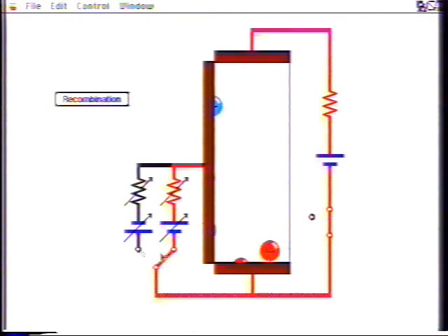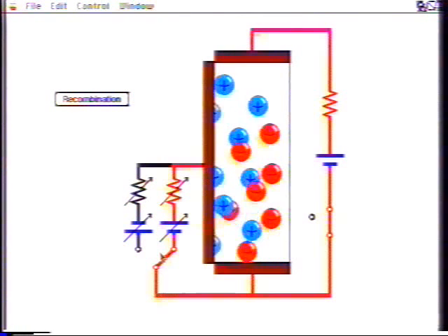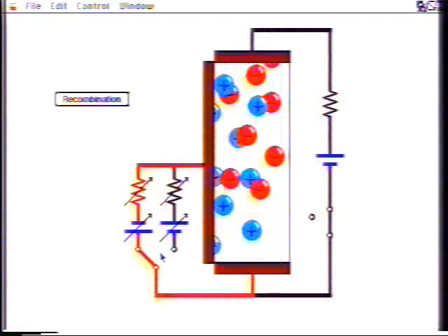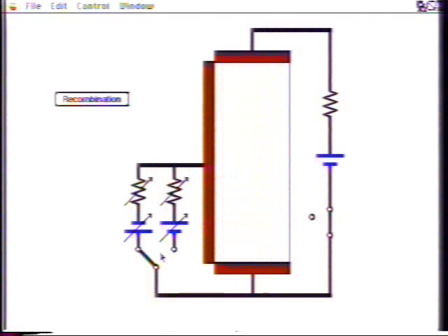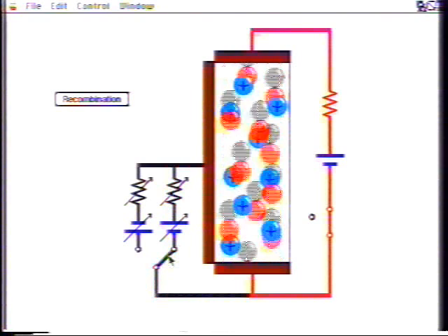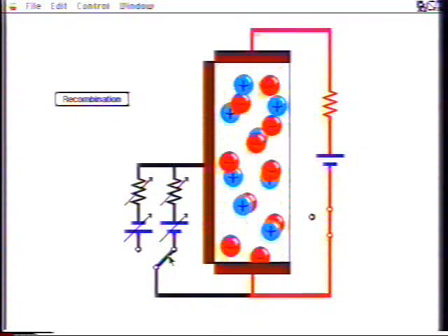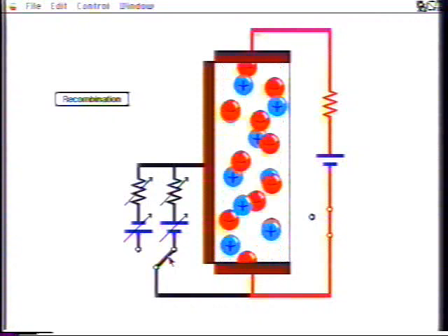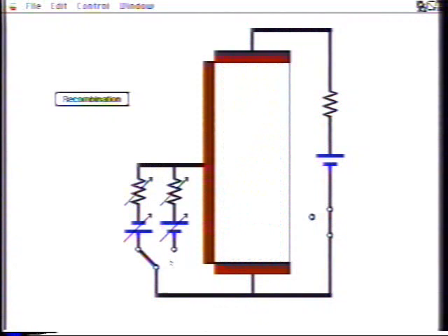The more positive charge is placed into the base terminal, the more negative electrons are injected from the emitter and are available to carry collector output current. The faster you want the switch to turn on, the faster you have to stuff positive charge into the base, requiring increased turn-on base current. The faster you want the switch to turn off, the faster you have to yank the positive charge out of the base, requiring increased turn-off base current.